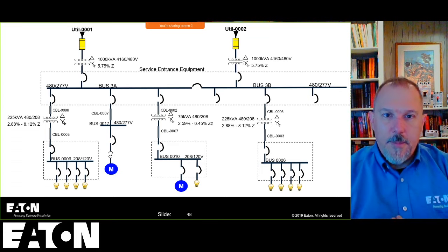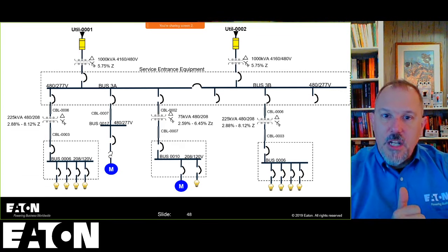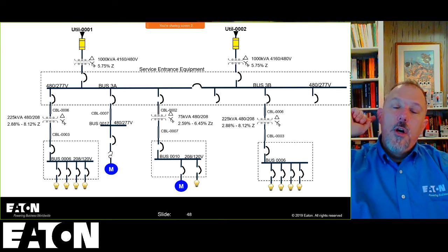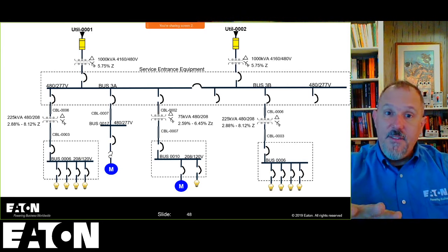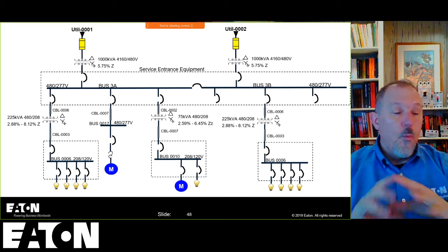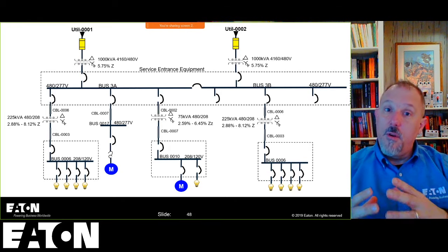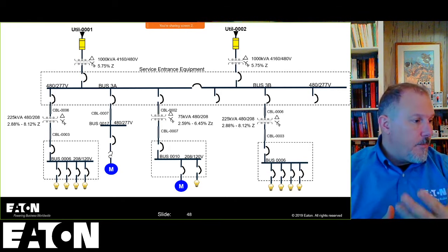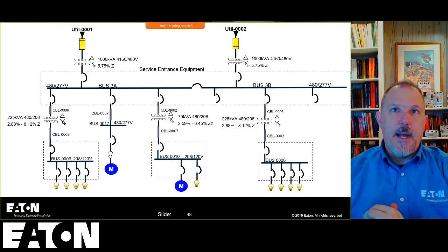When you change your power distribution system, you need to update your studies. And 70E tells us, remember, 5 years or when the system changes. So you may have to do it more frequently. Very important part of that piece of the pie.